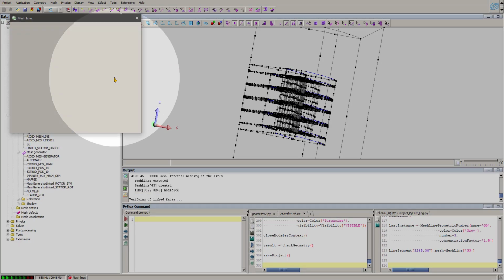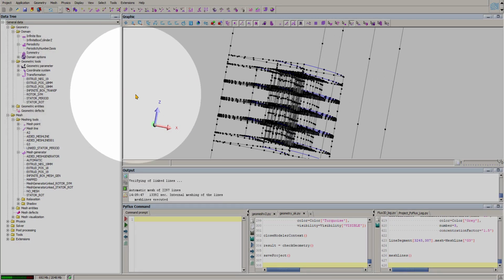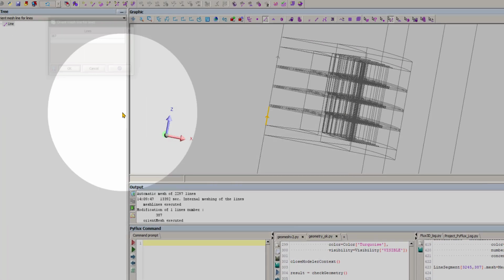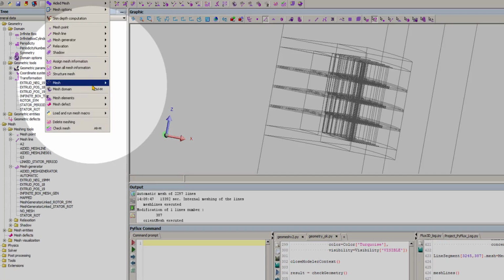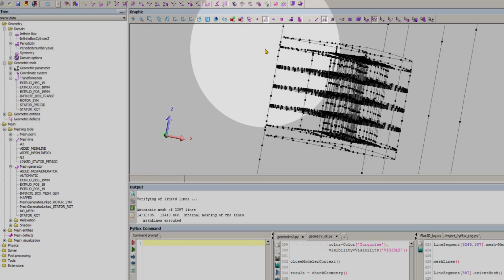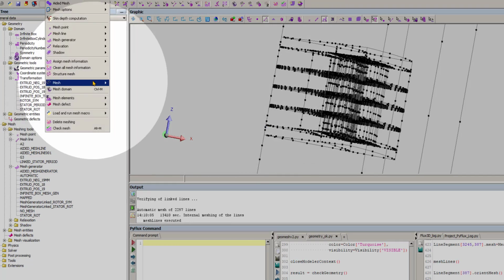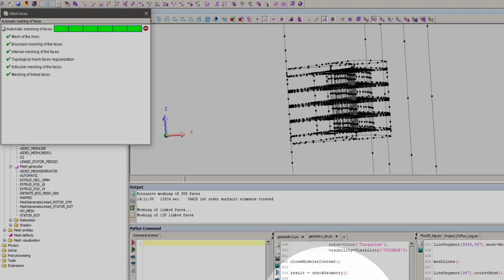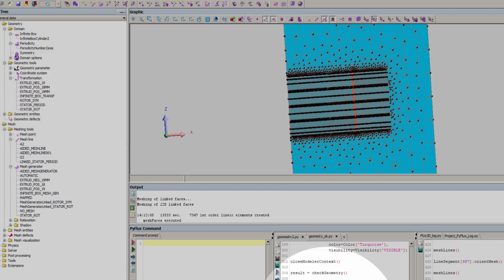to use a geometric variation instead of the arithmetic one. So then I can mesh, and as you can see, on the top it is good, but in the bottom it's not good enough. I will reorient the mesh again. And now when I reorient the mesh, you can see that the geometric mesh is very well assigned.